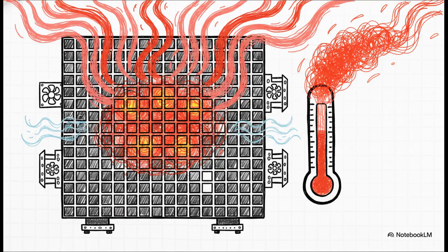But here's the thing. No matter what tech we're talking about, SMD, COB, or MIP, they all share one common enemy: heat. Getting that heat away from the electronics is, you could argue, the most critical factor for the long-term health of any LED screen. The tighter you pack those pixels for higher resolutions, the more intense this heat problem gets. Solving it is a massive engineering challenge that ultimately decides how reliable that display is going to be.